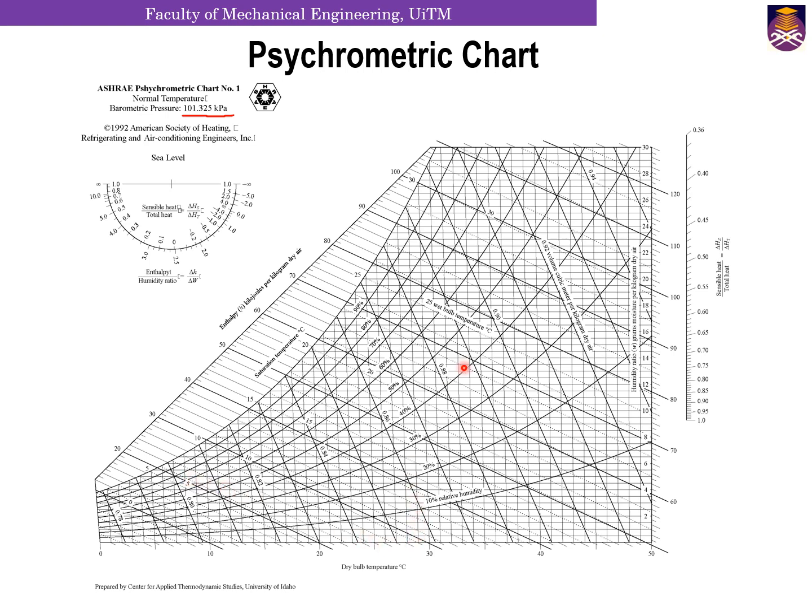Then you also have lines representing your relative humidity. So this is the line representing 10% relative humidity. You have 20% relative humidity, 30, 40, 50, 60, 70, 80, 90. And the last line here represents the relative humidity of 100%. Saturation is also known as relative humidity of 100%. So you also have saturation temperature given here.